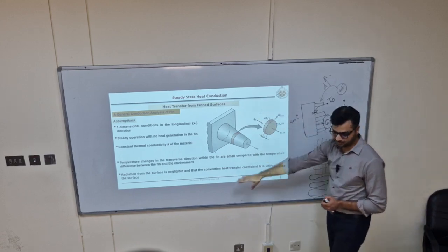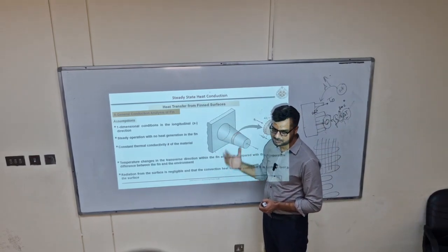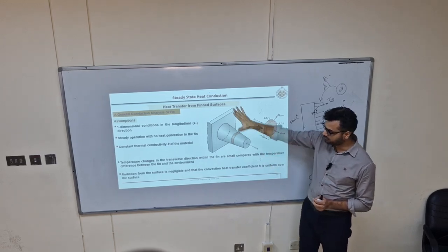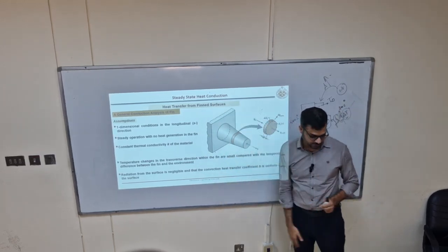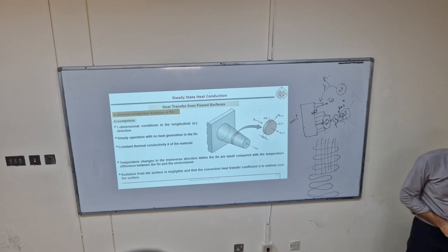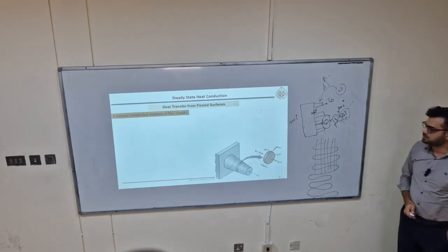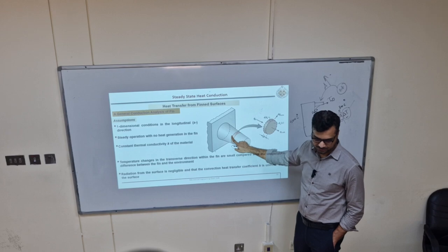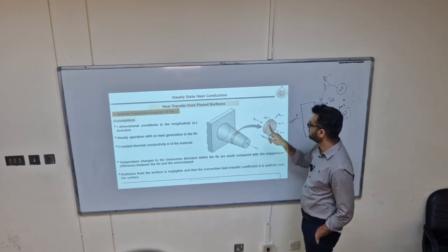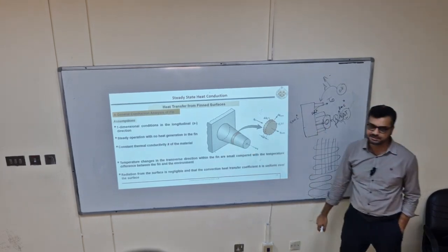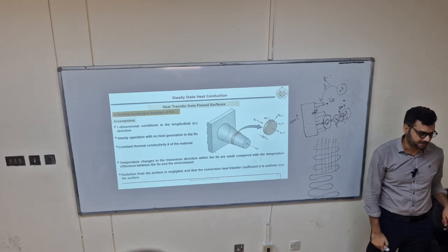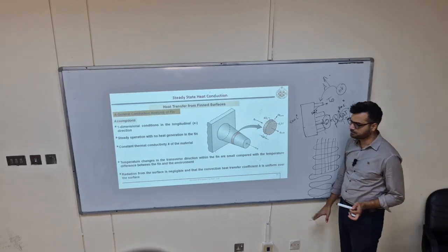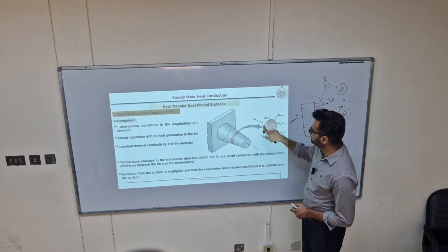Under these assumptions, we shall now derive its equations. And even under these assumptions, this derivation becomes so complicated. Again, what we do is take a differential element of that fin and write all the energies entering and leaving that element. No heat generation, no storage. So here is that small element which is taken out.